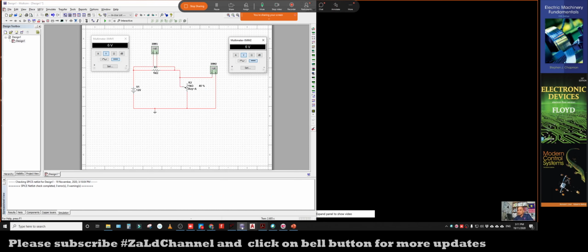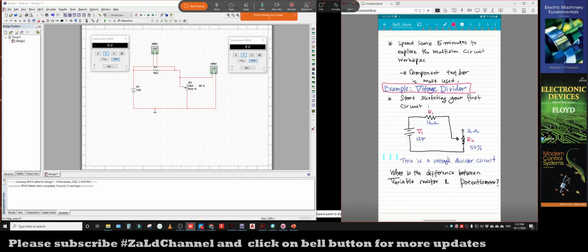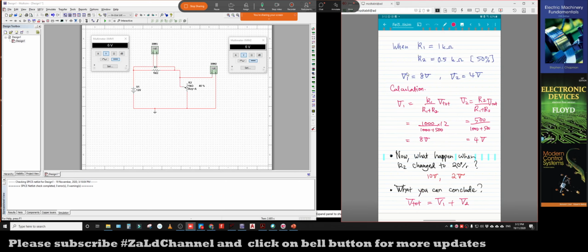So basically in voltage divider, let me just show you the lecture notes that I have shared with you. Here is some analytical explanation in terms of calculation. I have already given you the calculation. You can see this is the voltage divider circuit that we have simulated just now. Then another process is we want to simulate and then observe the results. So this is another explanation in terms of circuit, which is V total voltage 12 volt here is actually the sum of V1 and V2, where V1 is across R1 and V2 is voltage across R2.